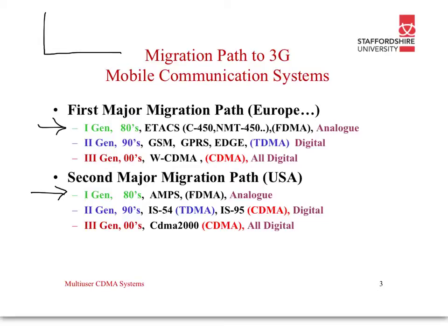So if I use this graph here, if this is frequency, then we would split the channel up into smaller bands, so there would be a lot of wastage because we needed some space between these bands, otherwise one user would interfere with another. Hence the number of users, or K, is limited in frequency division multiple access schemes by the number of frequencies. Hence this wasn't a very popular system. Another reason why it wasn't very popular is it wasn't very secure, because essentially somebody could listen in to the particular frequency and they could hear the message being transmitted.